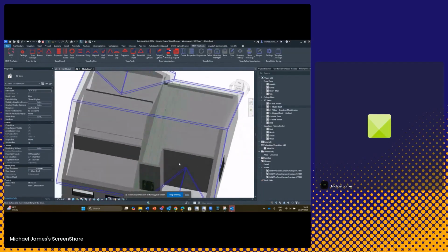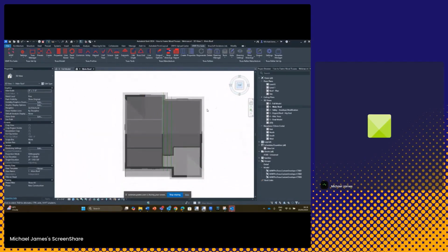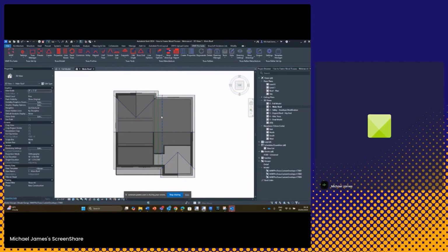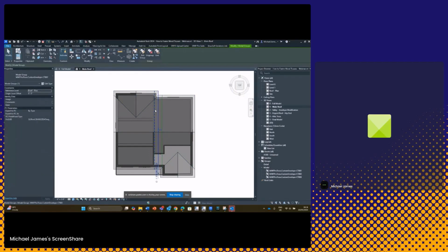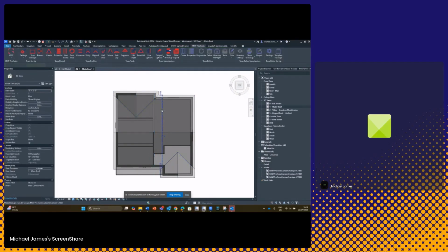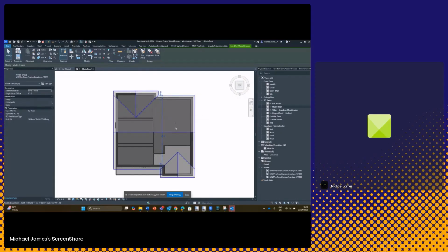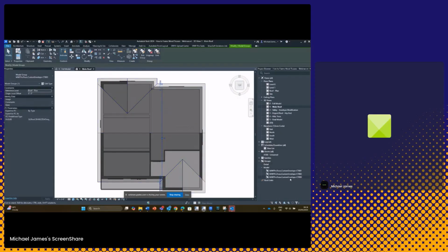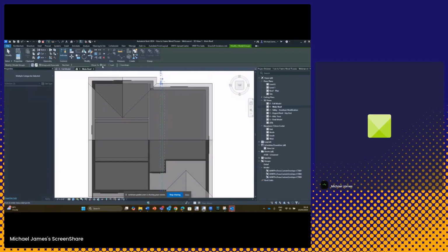And I want to copy these trusses so they span from start to finish. Okay, so I want them to be consistently spaced throughout. So I'm going to delete these two because I want my trusses to be, like I said, consistent. So I'm going to use the CT003 that I've just modified, and I'm going to use the copy tool or the array tool. And I can define the second point, number of trusses to array in this case.